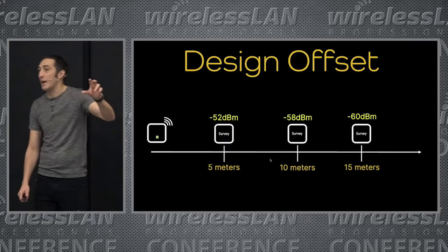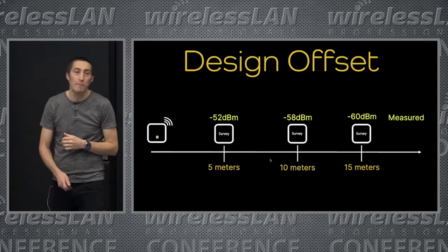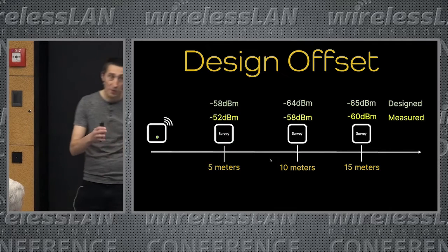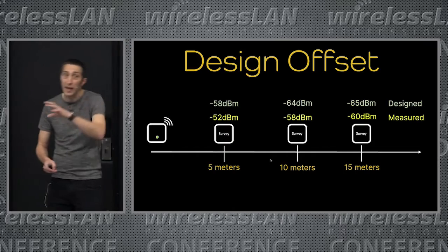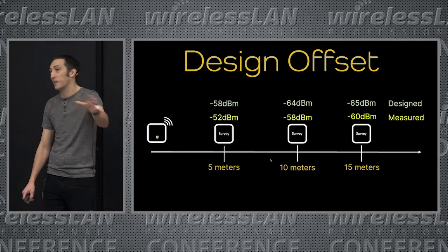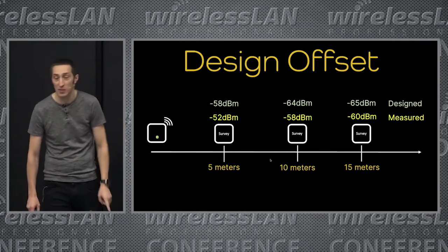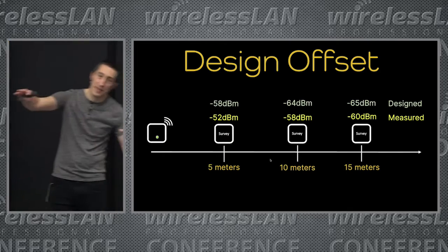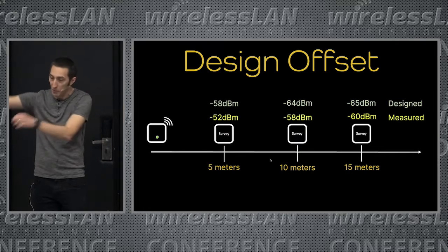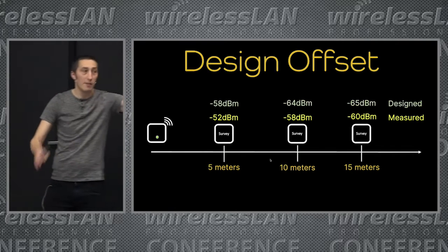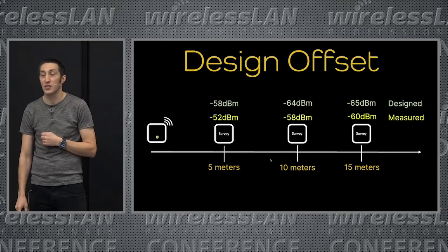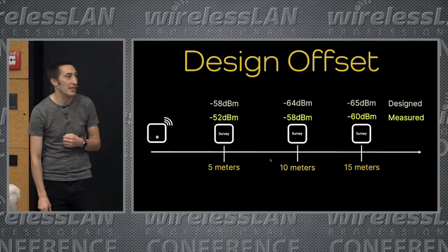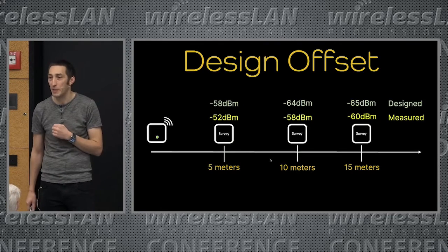When you do this, therefore, you're going to compare your measured data to your design data. And when I do this test, by the way, I'm doing it in free space. No walls, nothing like that. Okay, in a way, that's really important. Sometimes I even do it outdoors. Very often, I've got an area near my office where it's just big, it's open, and I put an AP up on a tripod and we measure it. Completely free space, so there's nothing in the way. That's also an important element of this. You want to make sure you've got clear line of sight to the AP.